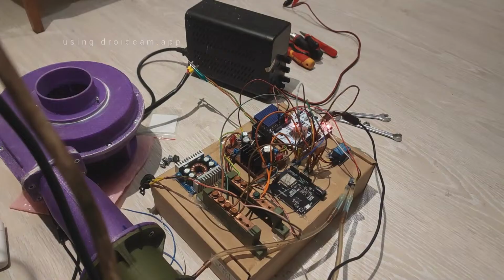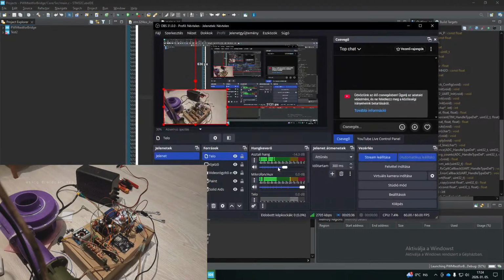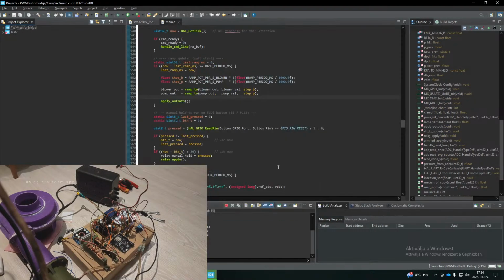What I will do now is upload the IDE's code, and I think I will build it. You can see that the code has built, and you can put it onto the STM32. Waiting for debugger connection. You can see that the thing is blinking red, and now it's done. Shutting down, exit, so we are done.